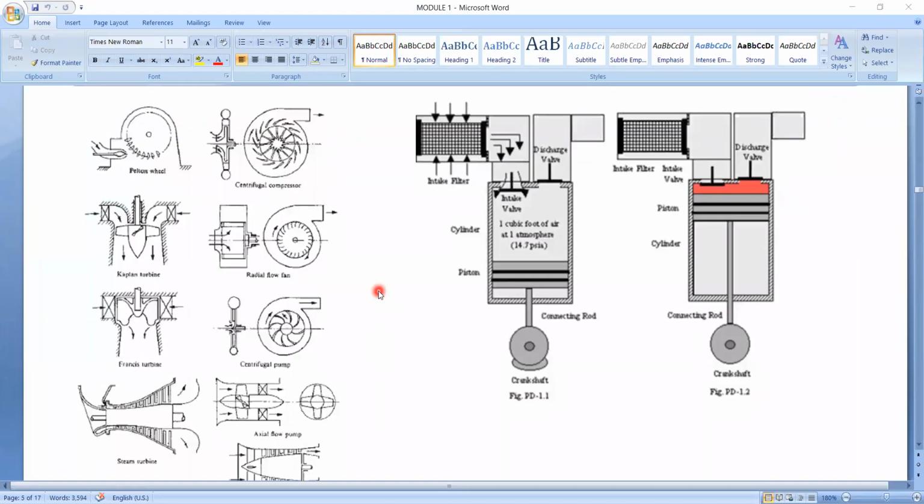On the other set, we have some other examples like tangential flow turbo machines. The best example for a tangential flow turbo machine is the Pelton wheel. A little consideration shows that this is a shaft, this is a runner, and over it we have a number of blades mounted on the periphery of the runner, okay. This is the nozzle which converts the pressure energy of the fluid into a high velocity jet, okay. So when the high velocity jet is impinging, it is in a tangential direction.